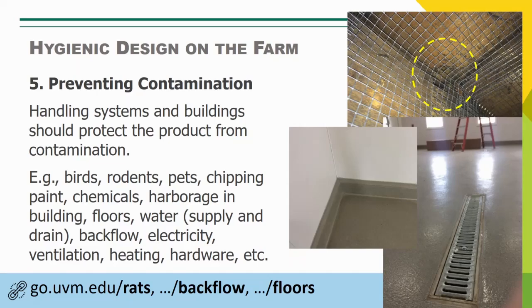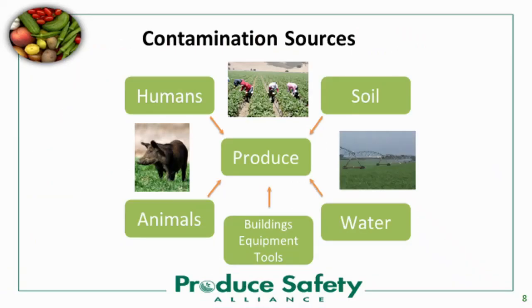And the bottom right photo is an example of a trench drain. This is a fairly narrow trench drain, but it's an example of an intentional floor drain that will help water get out of the area in an intentional way. You can see it's got a removable grate, just two bolts in this case, fairly light. That grate comes up to allow for access for cleaning and inspection as needed.